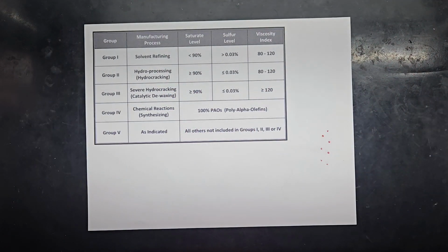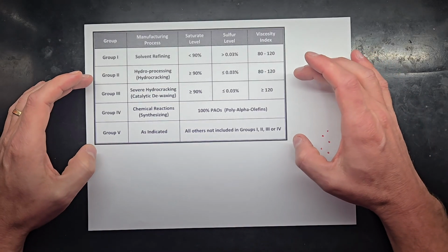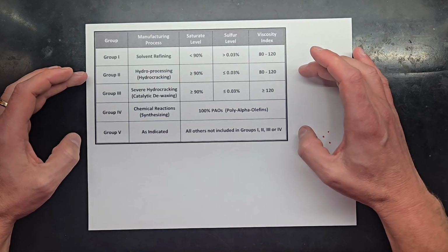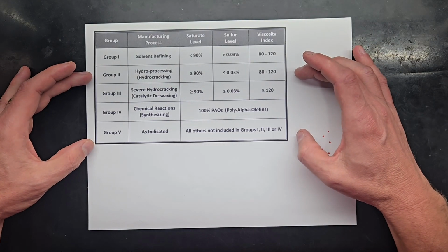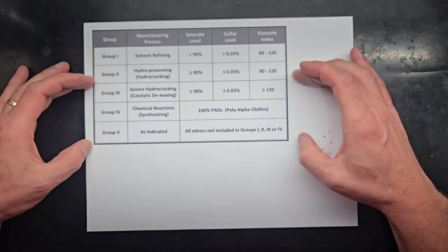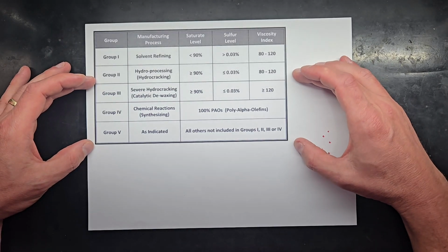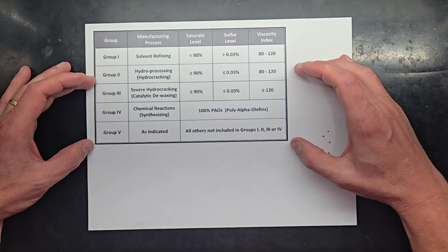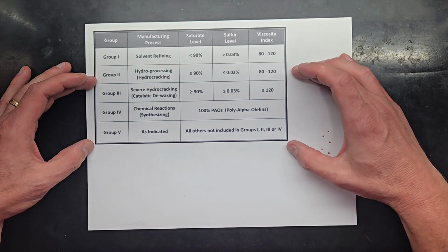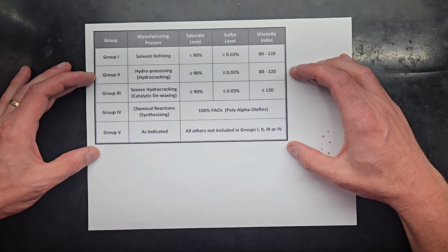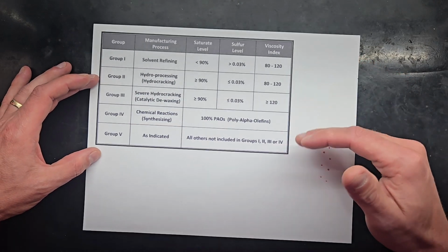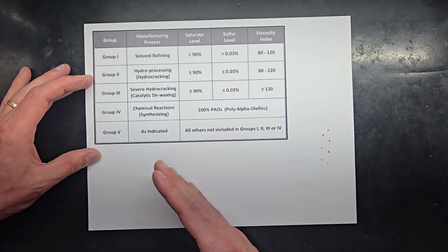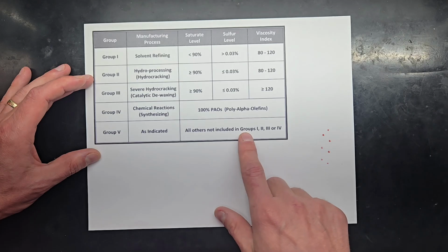As a consumer, that's one of those areas where I started to feel the most frustrated as I started to understand that better. When you're buying a product and it says fully synthetic, whether it's an engine oil, a gun oil, or a hydraulic oil, nobody's really telling you which of the groups of oils are used, or which base oil is being used if it is a Group 5.